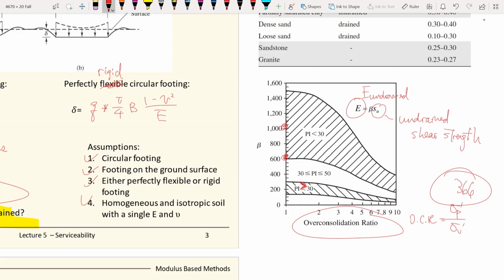So at this point, if you want to be a very good designer or very good engineer on foundation design, you need to truly understand soil mechanics. How is the stress-strain response of the soils, why the modulus values depend on the deformations. Are you designing for a small strain problem or large strain problems? What kind of deformation are you expecting for a design? Those will go into the next level of the details of geotechnical engineering design.